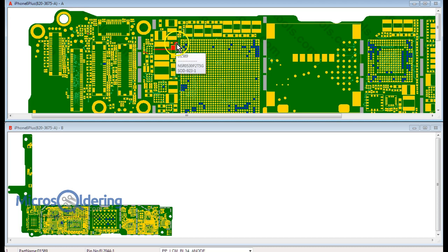So now we go to this diode. We want to make sure that diode is roughly 0.2 volts going one way and open going the other way, which it is. So now from the diode we go to the coil. In order to test the coil, you can put one lead on this diode lead, this side right here, and then the other lead on this side.